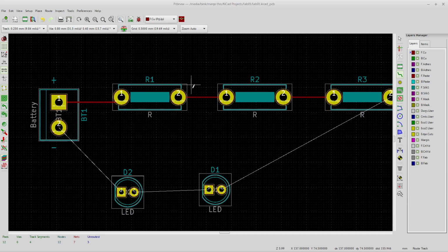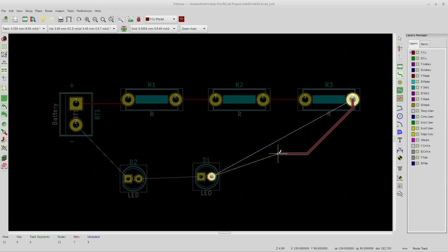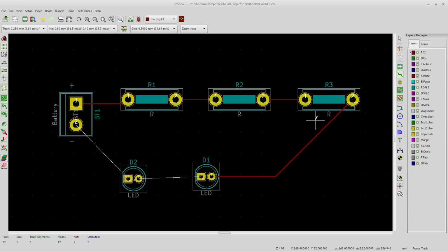Well, pretty soon, as your board gets even just a little bit more complicated, you're going to run into a situation where I need something from here to go up to here, but I just created a line right here and I can't go through it. I can't run a piece of copper over the top of the other copper there, and I can't exactly make a bridge over the top of it. You can make a bridge, I'll tell you that in a second, but you have to jump through underneath, so you can make a tunnel.